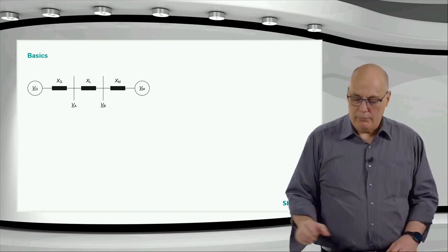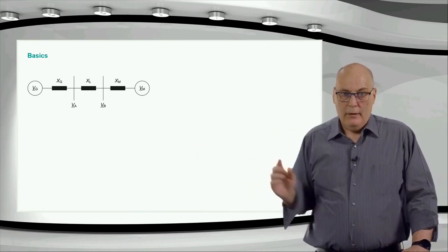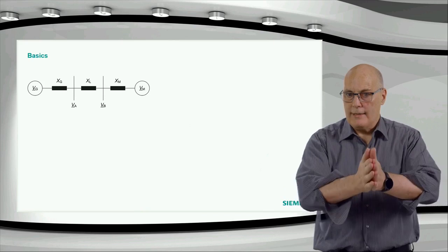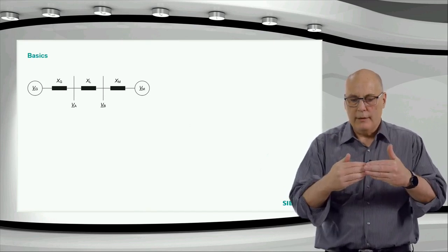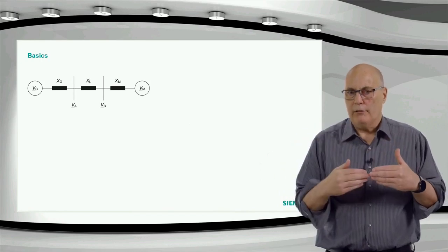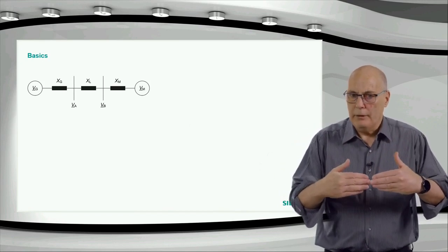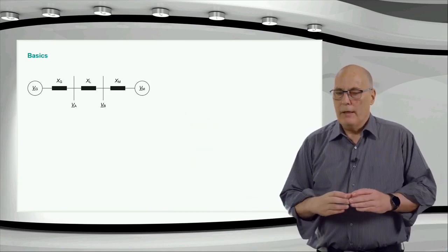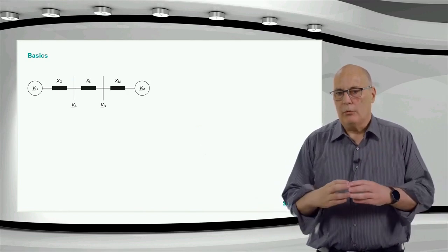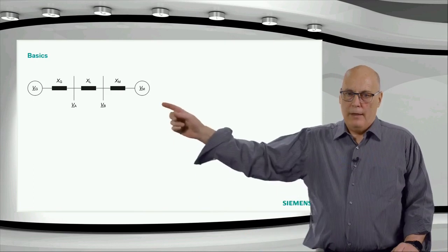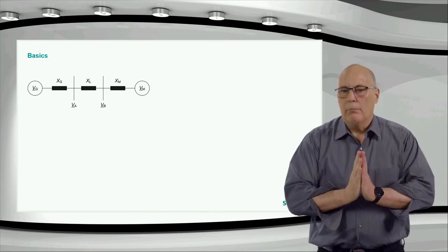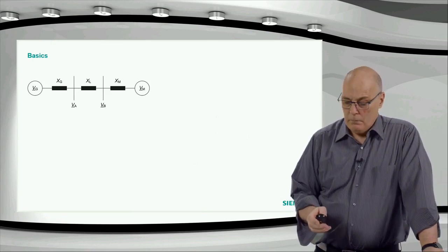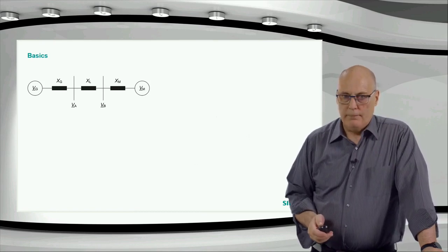If you place a relay at the bus A over here, that relay with its current and voltage measurement will look forward towards the XL, and a short circuit in front of it would be defined by the source impedance. That source impedance is all the generation behind it, that would be the VG and XG. That's our one equivalent source. You can reduce the entire source of that one relay to one equivalent generation. And the same in front of it, you can have the ZL and the remote bus bar as one equivalent load. So the two-machine model is very, very effective in analyzing and modeling the power system.